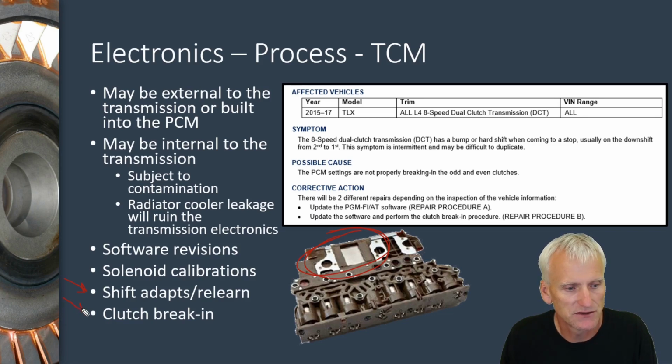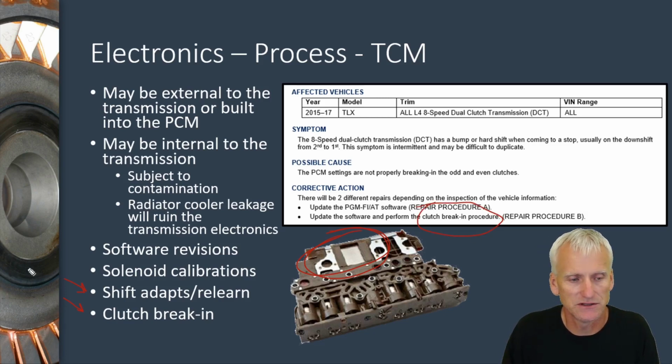Sometimes they'll have procedures, like this says clutch break-in. Just this example right here, this one's talking about the break-in procedure on this Honda. But there are other transmissions that sometimes, especially with a torque converter clutch, might have a break-in procedure, and that'll be done through software. So you tell it that you want to initiate that, and then it goes through the sequence that it knows it needs to go through to properly break in that clutch.